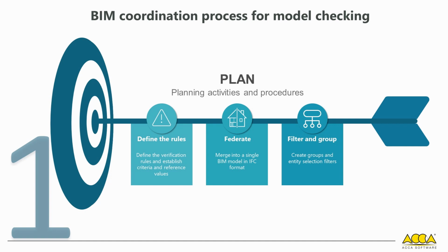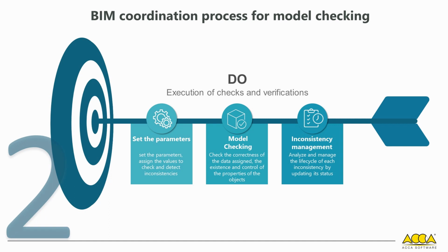Checks can be performed on individual models or federated IFC models. First, you create a filter to select the objects for verification, then define the rules that these objects must comply with. After setting up the controls, you initiate the calculation to analyze the data correctness and object properties.